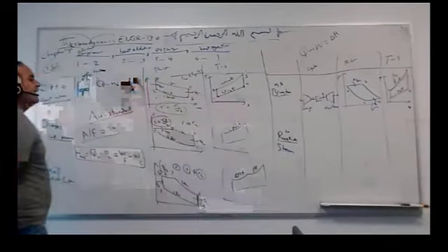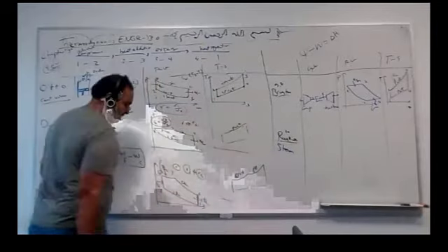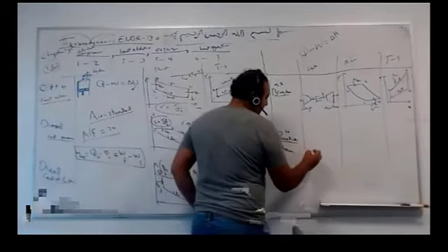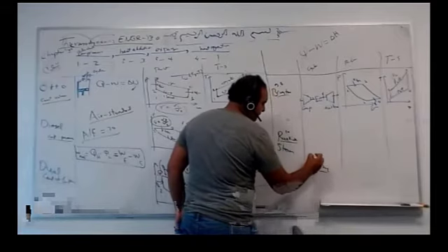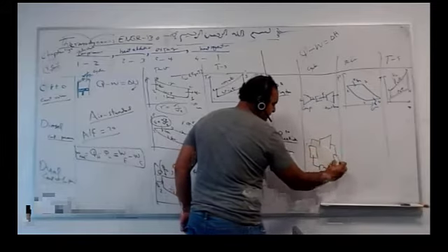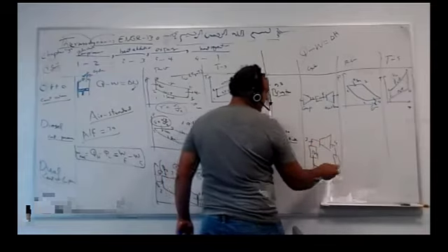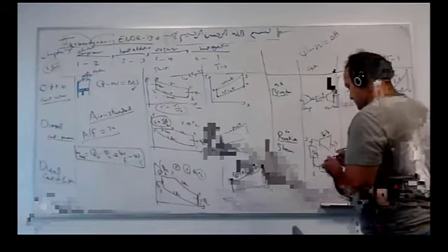But compression and expansion are always adiabatic. Everything is reversible. It's always isentropic here and isentropic here. Always you will see them vertical in the TS diagram, all of them. Even in Rankine. In Rankine, we have a pump, we have a boiler, we have a turbine, we have a condenser, and we go back. So we have the boiler, again 1, 2, 3, 4, and go back to 1. This is the turbine. This is called a steam turbine or power plant, Rankine cycle.